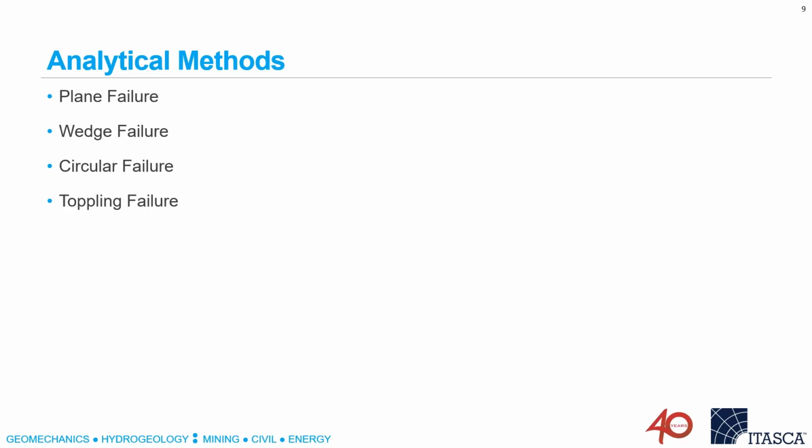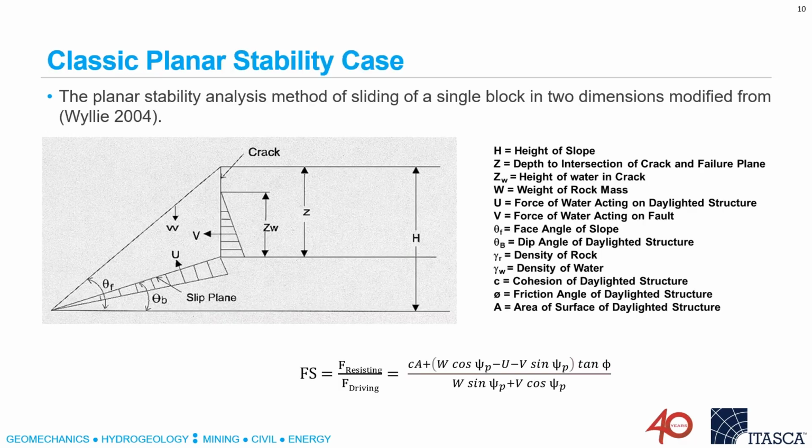But in between, there were analytical methods for simple failure mechanisms: planar failures, wedge failures, circular failures, toppling failures. There were relations and equations developed to calculate safety factor for various simple instabilities.